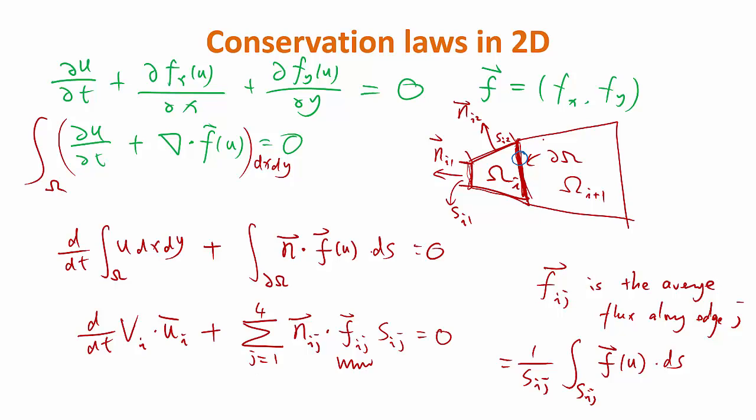All right, and this one-dimensional Riemann problem is exactly the same as our one-dimensional case because we are treating it as piecewise constant, and there is no variation in the tangential direction. There is no derivative in the direction along the interface. So the only derivative is normal to the interface, and we can use our one-dimensional conservation law. We solve the one-dimensional Riemann problem.